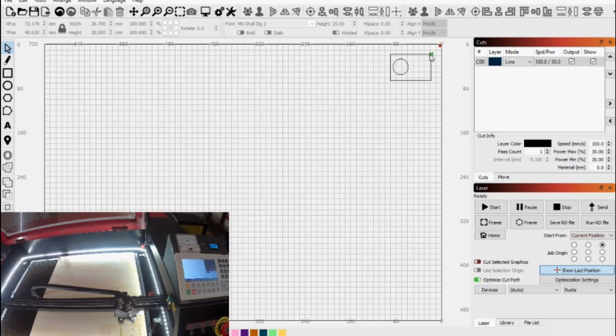Knowing exactly how to use that green square to your advantage is, to me, invaluable. I spent months really trying to get the hang of it. I spent a lot of time making jigs, running tests on scraps, and then trying to position the final material on the laser bed to get that position exactly where I wanted it. You may remember a previous video I made using a square on the X and Y axis and T-squares. That was part of my learning experience into how to operate this properly to my advantage, and you could probably put that in the archives, just not refer to it. If you understand this, it makes it so much easier to position your work on the workbed.